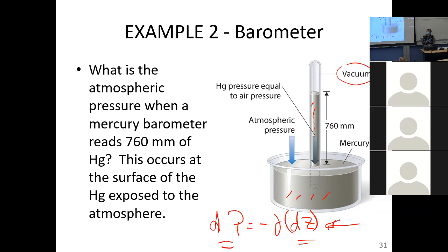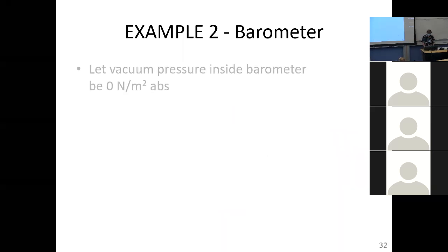And again, it seems so obvious that there's a continuum. When you leave here, in practice, it's not always that obvious. Why? Because all the pipes are underground and you don't know if some of the pipes are filled with air or not, because you have cavitation or some way of air getting into the system, backflow. So again, it seems obvious in a lot of the cases we look at here. When you leave here, that's the challenge. You never really know unless you can see the complete system.